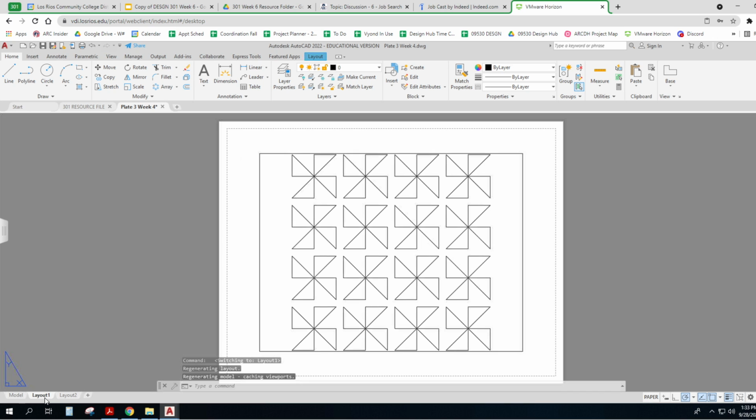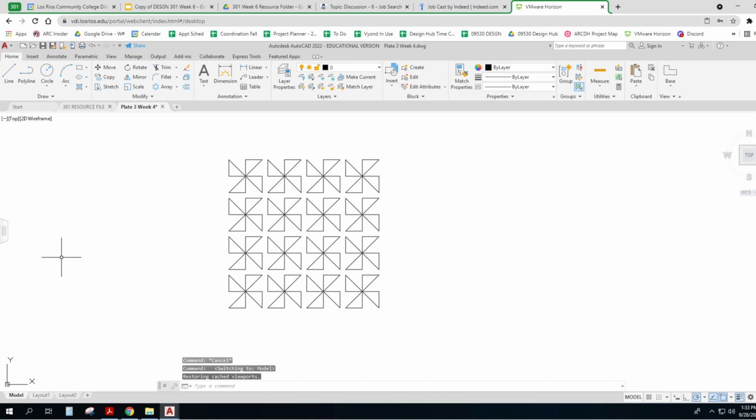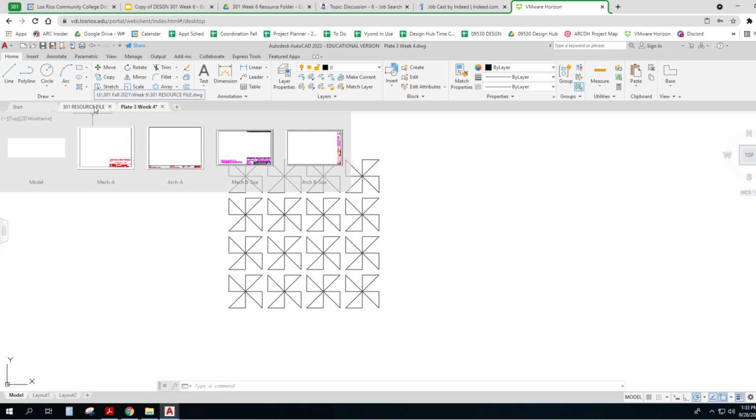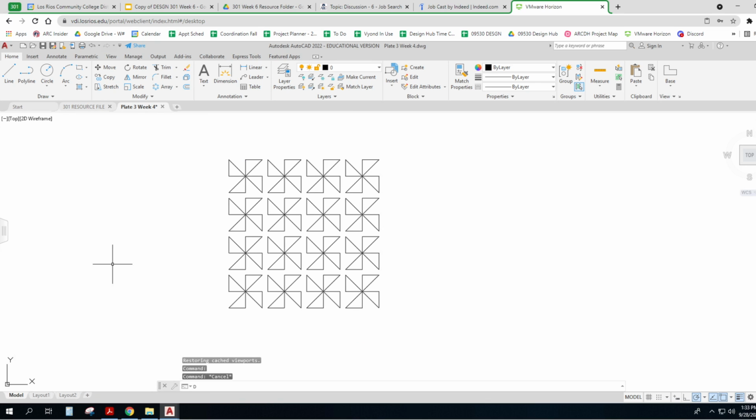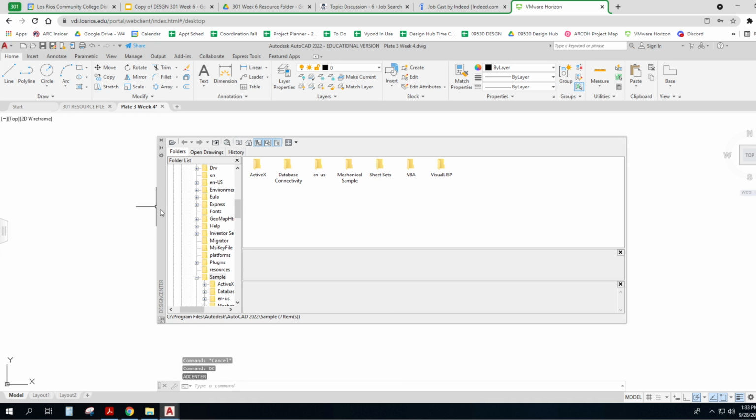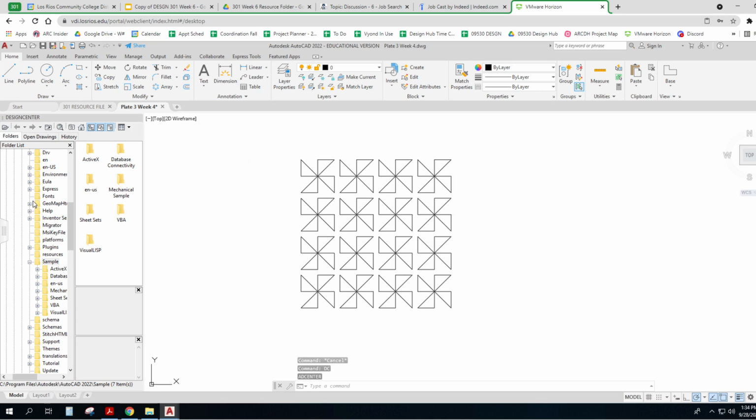So I don't have a title block down here, so I need one. And remember, what we do often, you can make one and set it up, but I go to a template file, a resource file, a title block file, whatever your company calls it, and I write DC for Design Center.